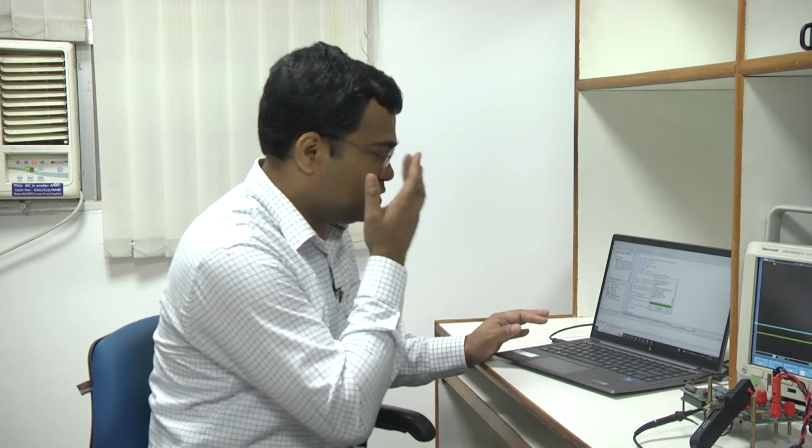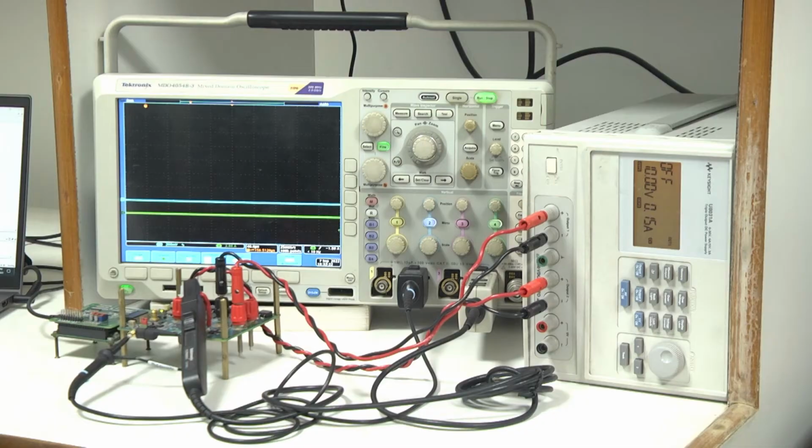Actually, this is a part of this lecture where we have already shown, using screenshots, the steps. First of all, we discussed in detail the Verilog code for implementing mixed signal current mode control in the 8th week, and in this lecture we have demonstrated the steps: the user constant file, then the main module, the submodule, how to instantiate, and then how to dump this code into our FPGA. So, I am not going to repeat that, it has already been dumped. Now, we are going directly to the hardware.